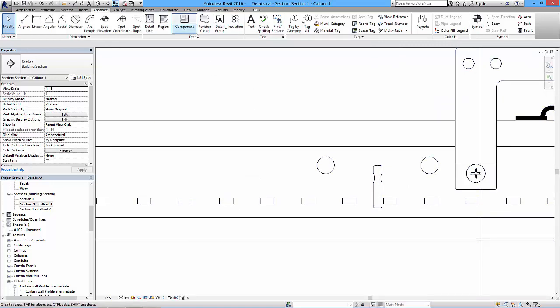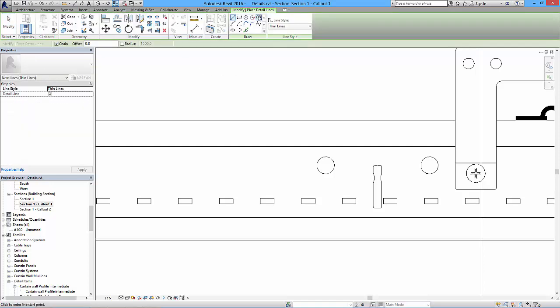So that's making this look uniform, and we can do a similar thing with these circles, if you wanted to as well, but we'll just go detail line and create a circle. If we can't snap to the midpoint of this or the center of the circle, SC for center circle, and that will pick up the snap, and then we've got that shape drawn.